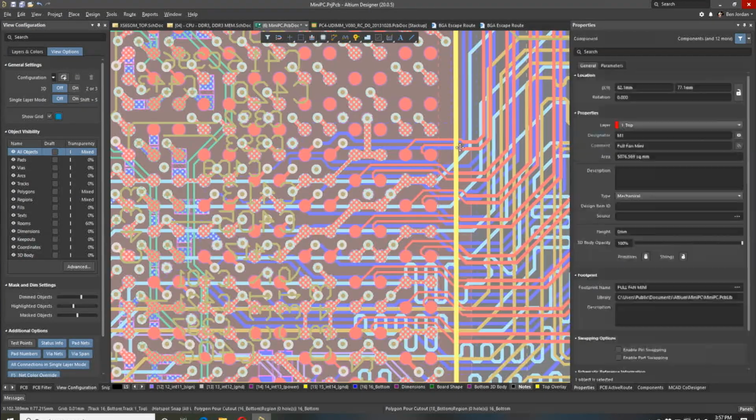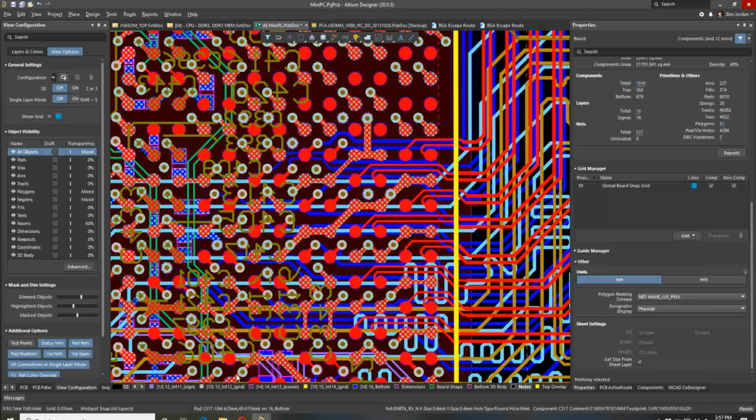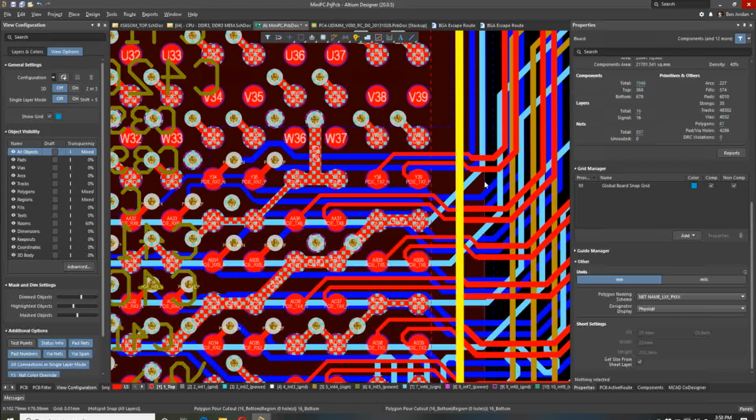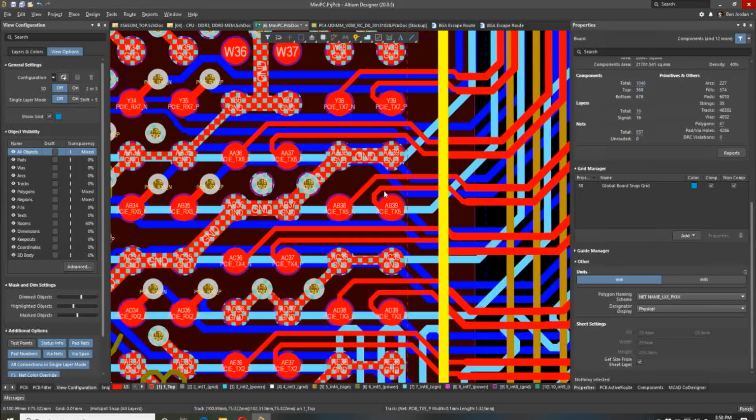This here on the top layer. Am I on the top layer? There's a lot of layers in this board. Now I'm on the top layer. So you see this here, this thin line? That's the edge of the room. So we couldn't see that before. And you'll see that the moment these segments cross over there, these diff pairs for the PCIe bus neck down nicely and do a really neat entry in here. So this is another trick you can use.